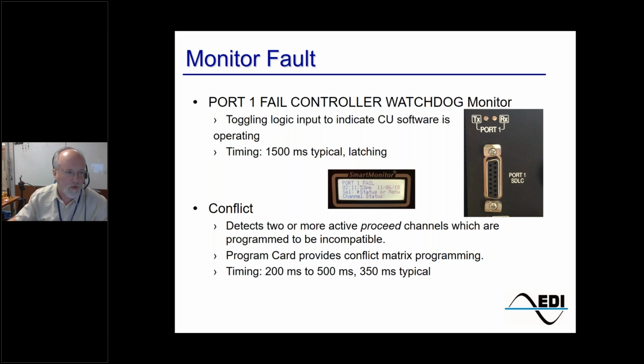So on the monitor, if you ever get this port fault, you're going to look at all your connectors with your SDLC. The first thing I always do is look at the monitor, make sure that the TX and receive lights are flashing, and they should flash. If they're not, that would tell you that the connector is either not connected correctly, or the wire itself might be bad, or the connector might be bad.